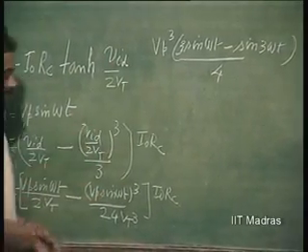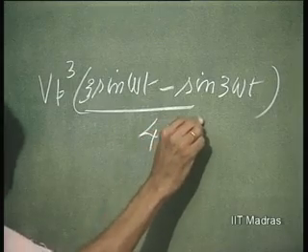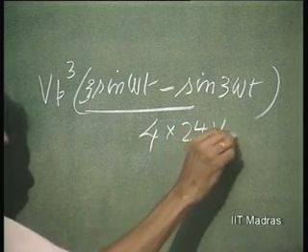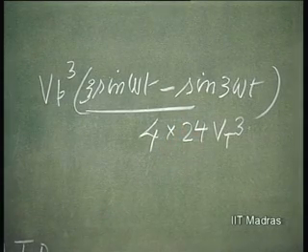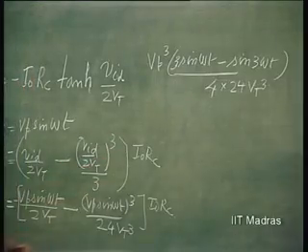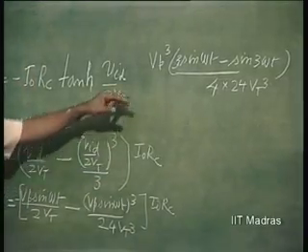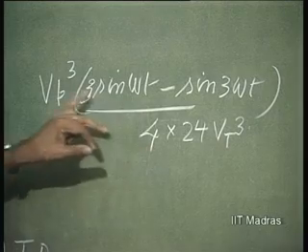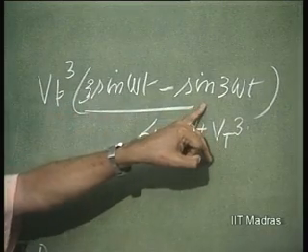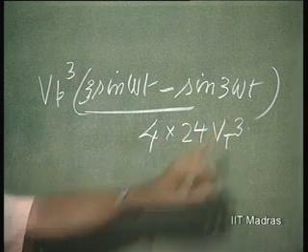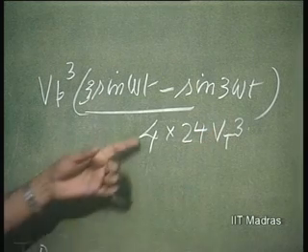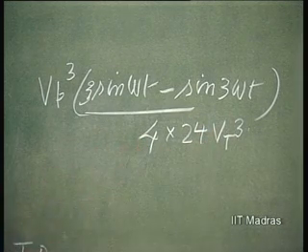Okay. So, that divided by 24 Vt cubed is what is going to remain of this, right. So, this factor therefore, is going to contribute to certain amount of distortion because of the third harmonic. Okay. So, the third harmonic distortion is going to arise here.